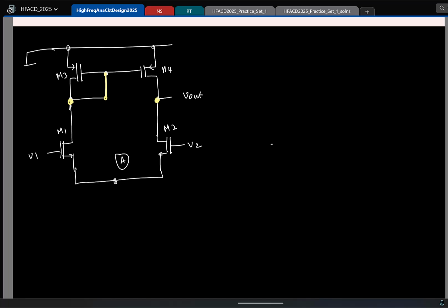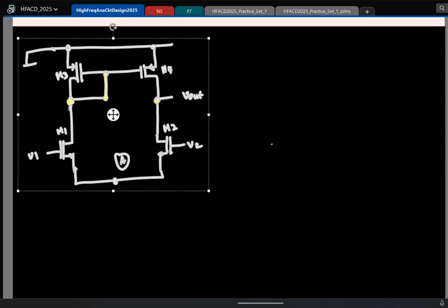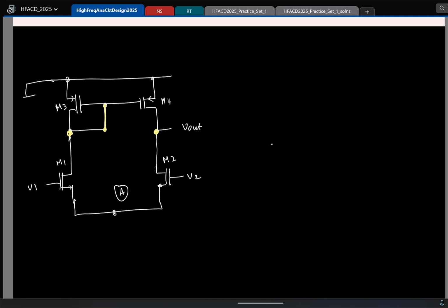So at least if I decompose now as common mode and differential mode parts, for common mode inputs, this becomes simpler, right? So let's take a stab at it and try to find the response due to common mode and differential mode. Again, only for common mode we can use symmetry, but let's do that and see. So again, I'm looking at common mode inputs, which means both inputs have the same change VIC, right?